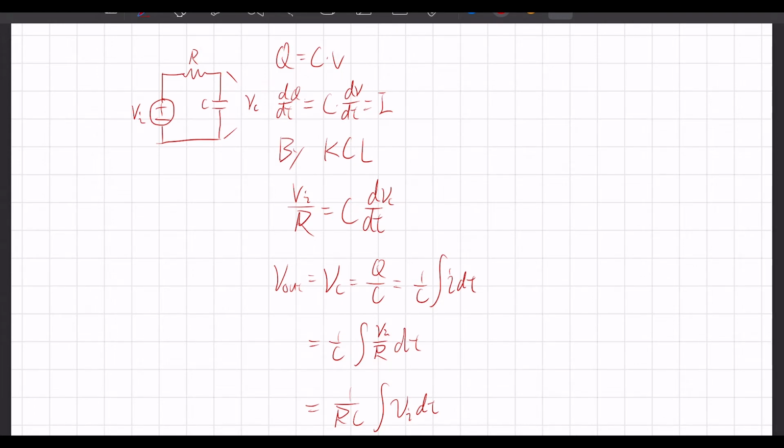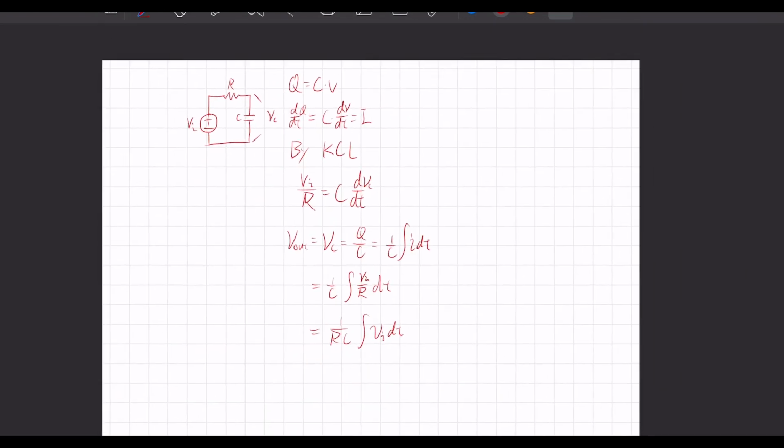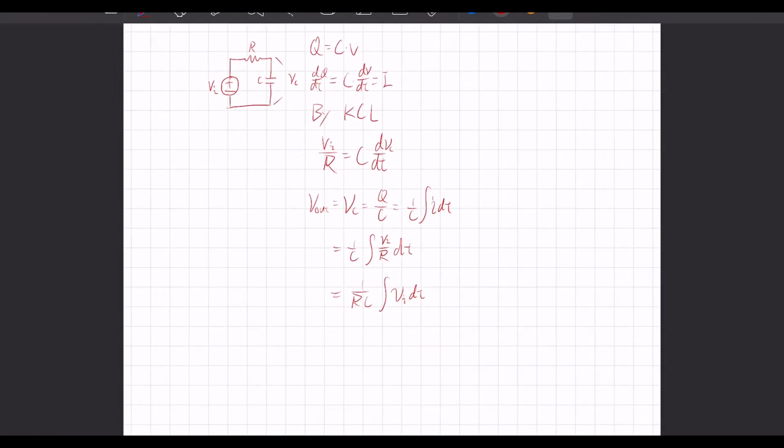But we still find out that the output voltage of the above circuit is too small, so we will use an amplifier to amplify the voltage. According to the calculation formula of the amplifier, it can be used to adjust the output magnification. By the simulation's results, the output voltage amplitude of the RC circuit is about 0.6 volts. We probably need a magnification of 10 times.